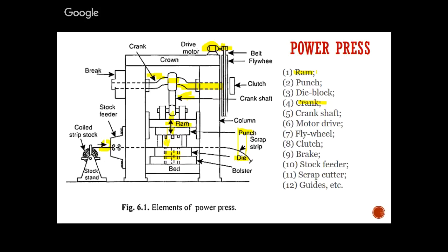The crank and driving shaft are generally connected by means of belt drives or gear drives. If you use belt drives, you have a stepped belt drive, in which you get different speeds by changing the pulley from one diameter to another. If you use a gear system, you have a first gear, second gear or third gear with different diameters. That diameter helps us get the desired rpm. According to that, the ram will move forward or return stroke, according to our timings and the rpm given by the drive motor.